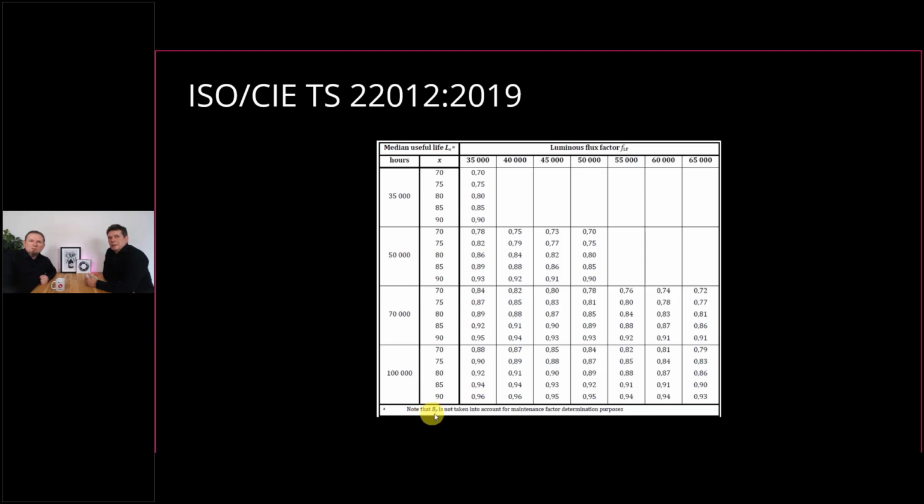There's also a B value. It's just mentioned here. For all this, we have this median useful lifetime, and median means B50. B50 is something the whole industry, at least in Europe, has in consensus that everybody should deal with and publish just B50 values, because this is the median, the middle of these values of this loss, of a spread of different luminaires. And yeah, that's why it's 50. So if you have a B10 description on the data sheet, there should always be also a B50, or it's also possible to recalculate, but then you should know the luminaire.